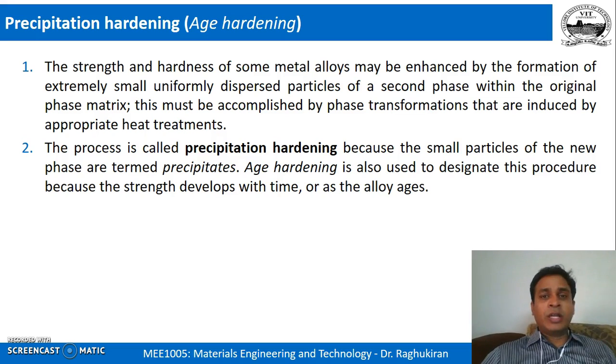That is in liquid. In solid, can it happen? Yes, that happens. You take a supersaturated solid solution of any two elements, say a very classical example is aluminum and copper, and you leave it for some time, then what happens? The supersaturated copper in aluminum solution precipitates out, and if it is liquid, it will settle at the bottom, but in solid it cannot go to the bottom, right? So it will precipitate out and it will be there everywhere in the aluminum matrix.